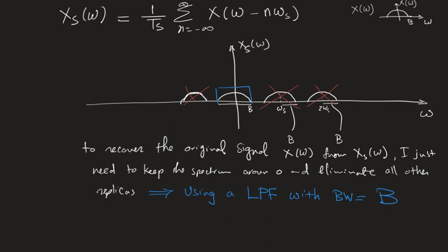That's very interesting, right? But from a physical point of view, it has a meaning. A low-pass filter does what when you put impulsive signals into it? It tries to interpolate between them because it doesn't drop very quickly. When you have a low-pass filter, like an RC circuit, for example, when you put a value on it and then make the value disappear, because of the capacitor it will not disappear immediately. It will try to drop slowly. And then you get the next value, so it's going to interpolate between one sample and the next one. That's physically the effect of a low-pass filter.